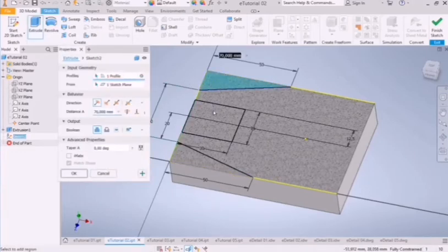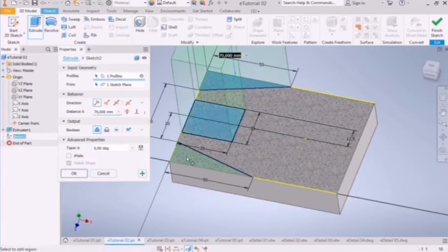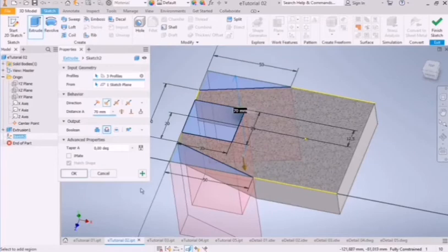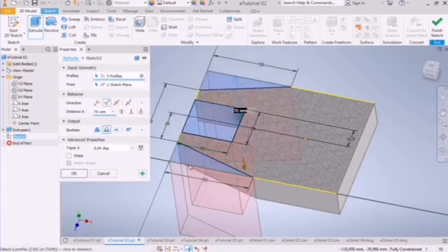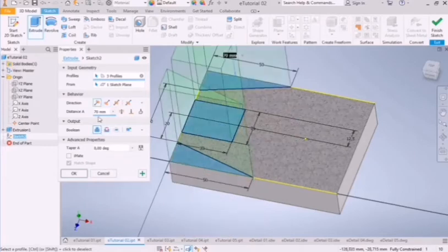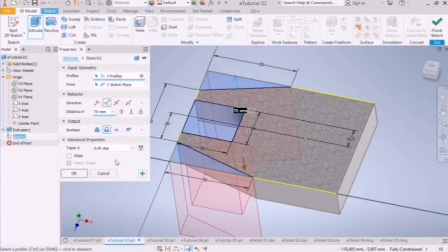We select 1, 2, 3, and then we go to cut. It's red. Let's change the color. That one is join, as you can see the color. Once it's light red like this, it means it's cutting. It already automatically changed the direction. That was joining, and see the direction automatically changed without selecting. When I click cut, it changed the direction. Then we say okay.